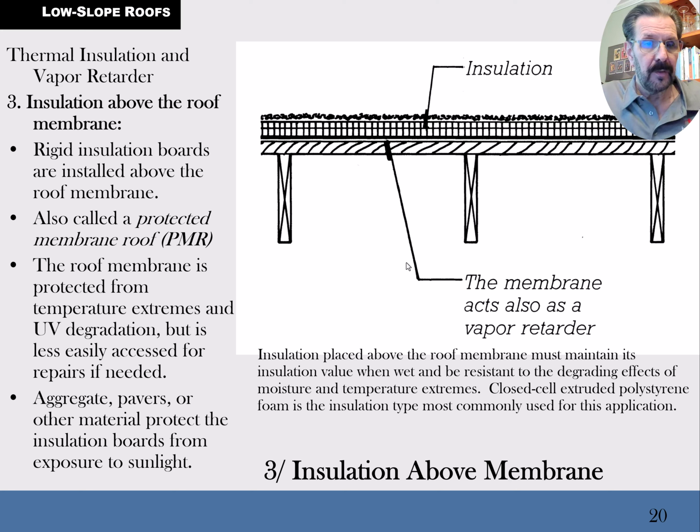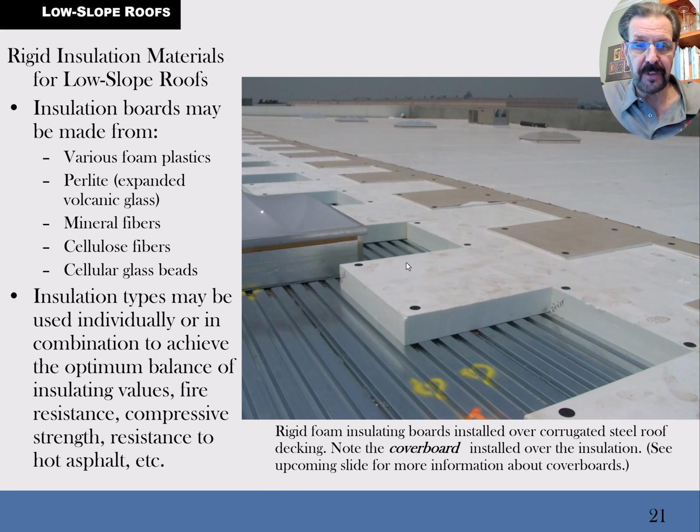Okay, so called a protected roof membrane, PMR sometimes. Okay, I'm not going to make you memorize that abbreviation or anything, but anyways, that's the other model. So here's an example where actually this is not the third case. This is the second case where they've got the insulation, they've got some kind of plastic members that are turned in to give you a friction grab at each corner of these chunks of insulation to hold them down, and then they're putting a